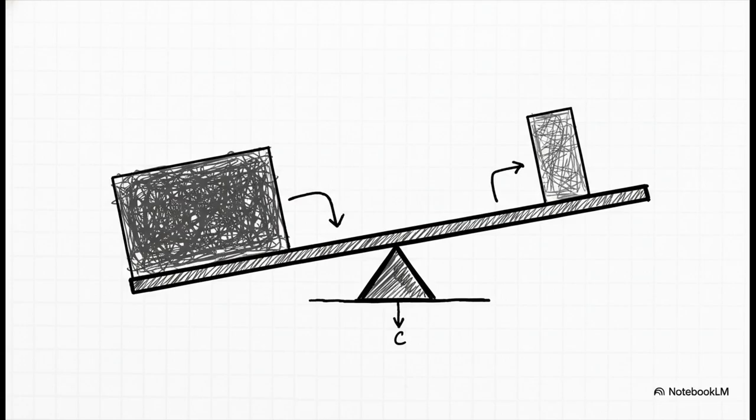In our I section, the top flange was way wider than the web, so it had more area weight. The crucial point is, you can think of it just like a seesaw. The heavier person makes the balance point shift. The larger top flange pulls that overall balance point up towards it. This is an amazing intuitive check you can use in your exam to quickly see if your answer even makes sense.